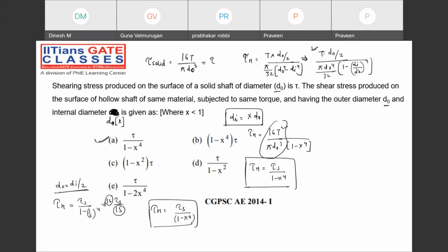But assuming the conditions, whatever the solid shaft's torque transmitting capacity is, you just thought that the hollow shaft will also have the same capacity and you have applied the same torque. In that condition, the tau value for the hollow shaft will exceed the yield stress value and it is going to fail first because it is 16 times the solid shaft. Understanding the meaning?